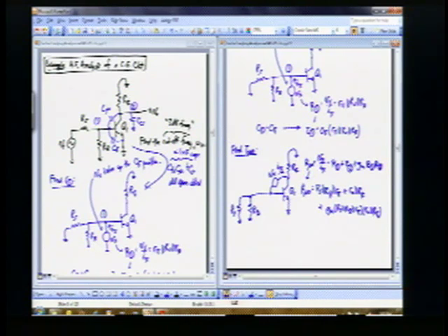Okay? And so we have that driving point resistance, and so we can now write that T mu naught is equal to R mu naught times C mu. So there is our second time constant that we're going to need to determine the frequency response of this whole thing. Okay? Any questions about what I just did here? Any questions at all? There are no stupid questions.